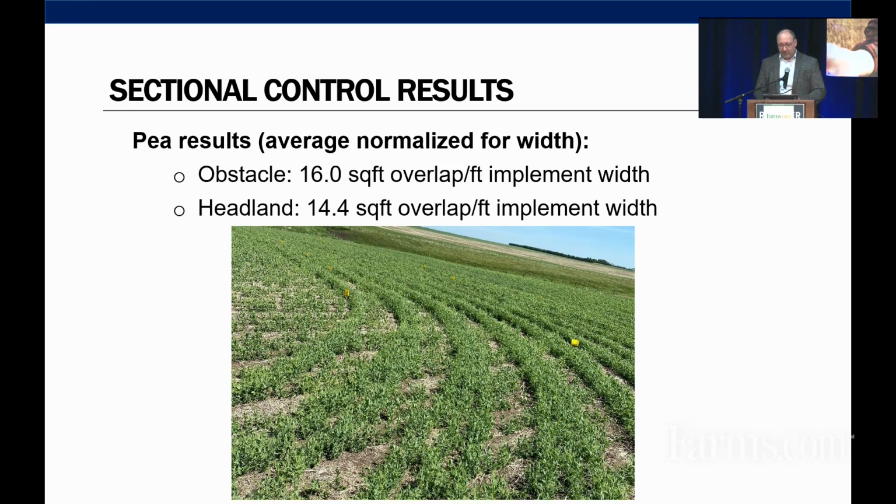Now, one of our hypotheses was that it's the fan speed that's making some of the difference when you're looking at the seed distribution in an air seeder. We haven't gone through and had that step validated, but that was just something as we're looking at what's the difference between peas and canola. That's one thing to consider, is fan speed, and how that look-forward and look-behind time impacts your distribution system and the amount of seed that goes into the ground at the time.